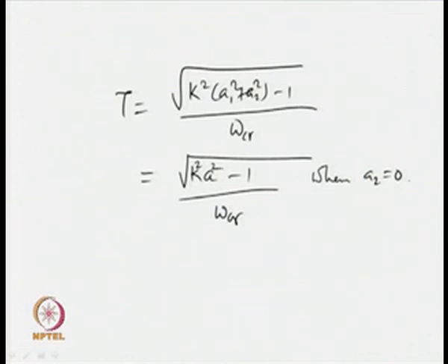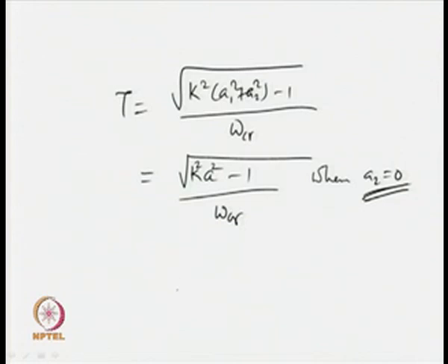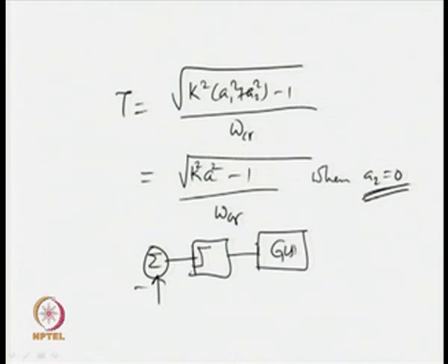When you have got A2 equal to 0, when I have no controller in the loop, or to say when I use offline identification scheme, at that time A2 becomes 0, and we have an identification scheme which can be given in the block diagram format: a relay and a process put together in closed loop with negative feedback.